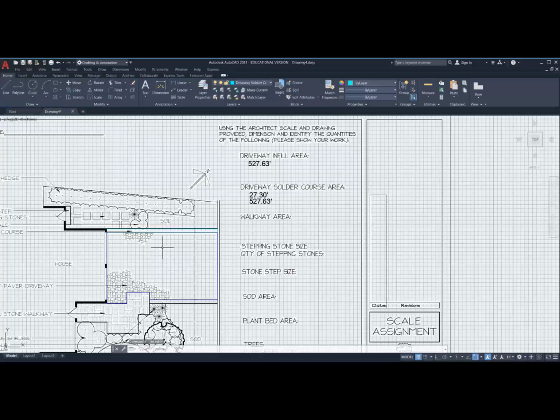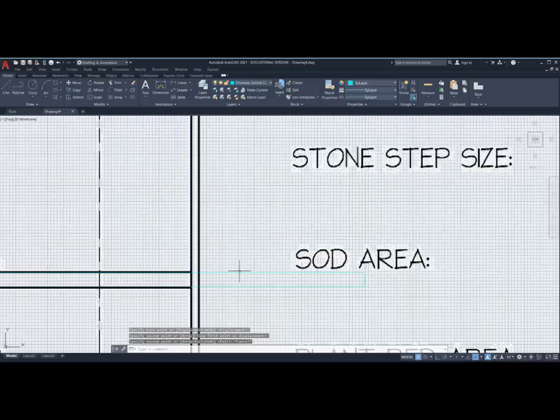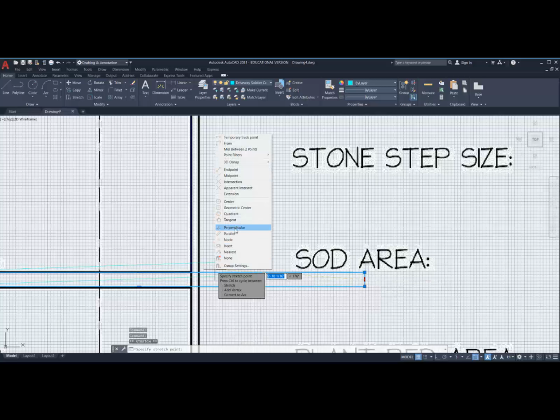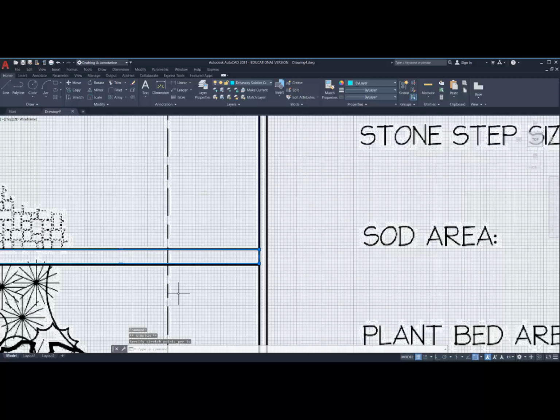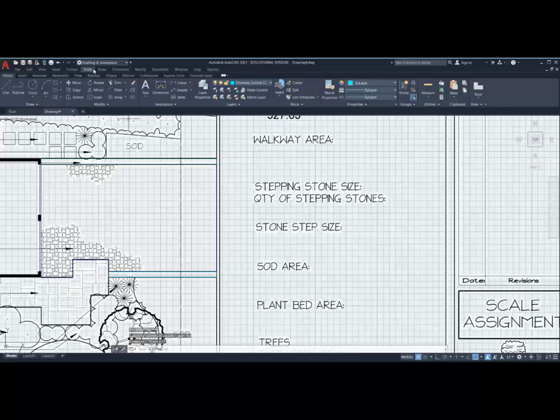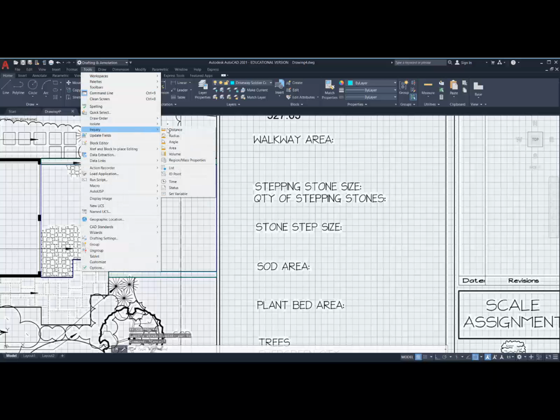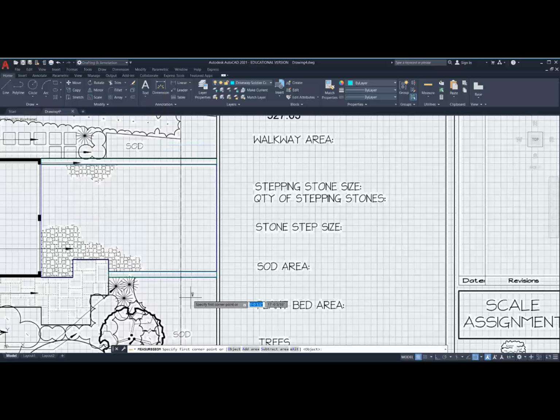And I can use other techniques. Now I can copy this area because I have the right width from there to this point. So it's the same width on both sides. And now I can move this polyline from this point to be perpendicular with that line there. And I'll do the measurement there. Tools, Inquiry, Area.